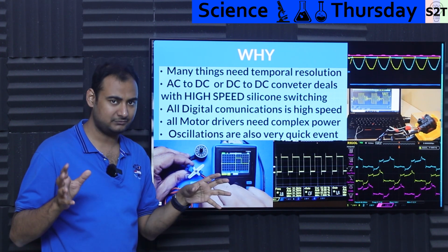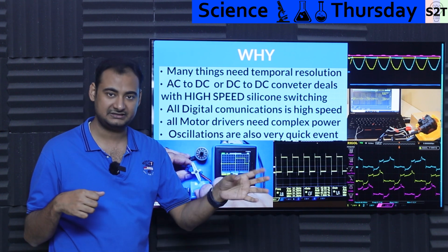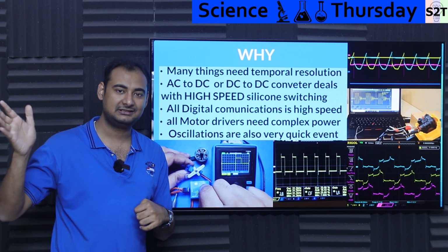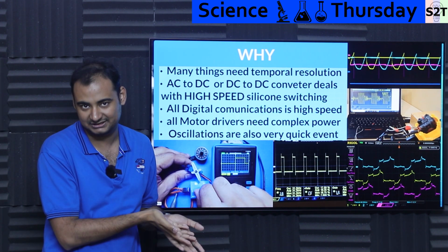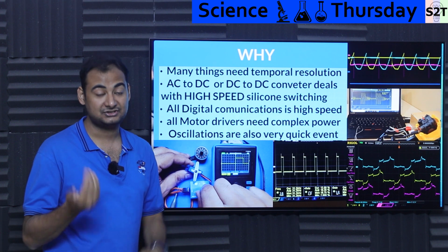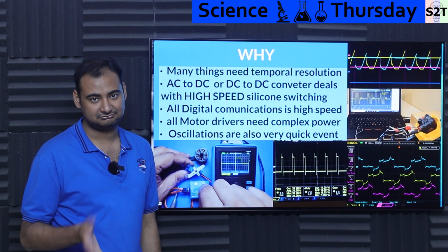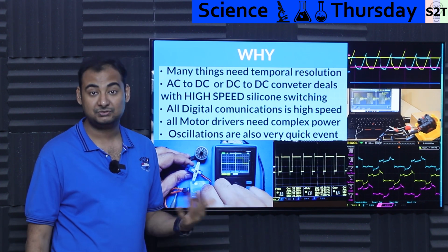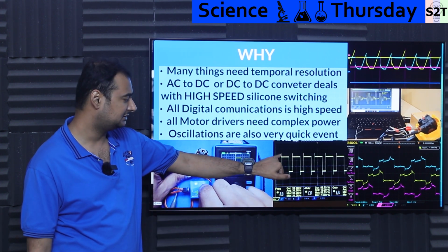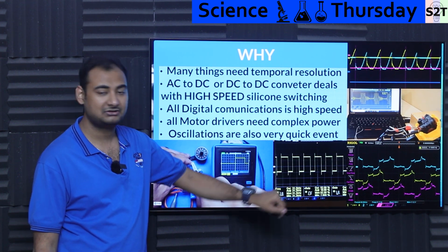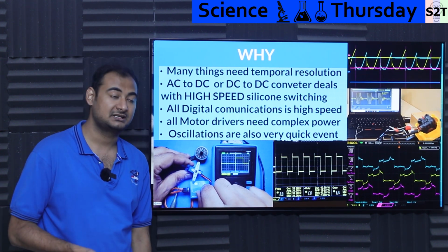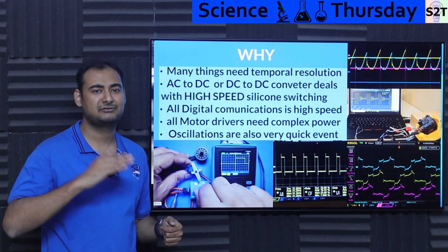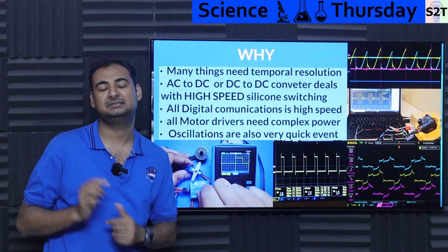So digital communication requires high speed, and it requires you to clearly see that the signal is going up and down. Now be mindful, the producer instruments and receiver instruments are designed to just assume it works. They assume their electrical engineer did their job properly and the signal they are sending is properly under spec. And the receiver is like, I'm assuming the signal they are sending is properly under spec, and then I'm just going to work based on that. But when you put an oscilloscope on it, you can see some odd behaviors, like, hey, there is a little bit of overshoot, hey, there is a little bit of undershoot. Now again, if it's sensitive equipment, you may be like, yeah, we gotta fix this, or it may be like, who cares?